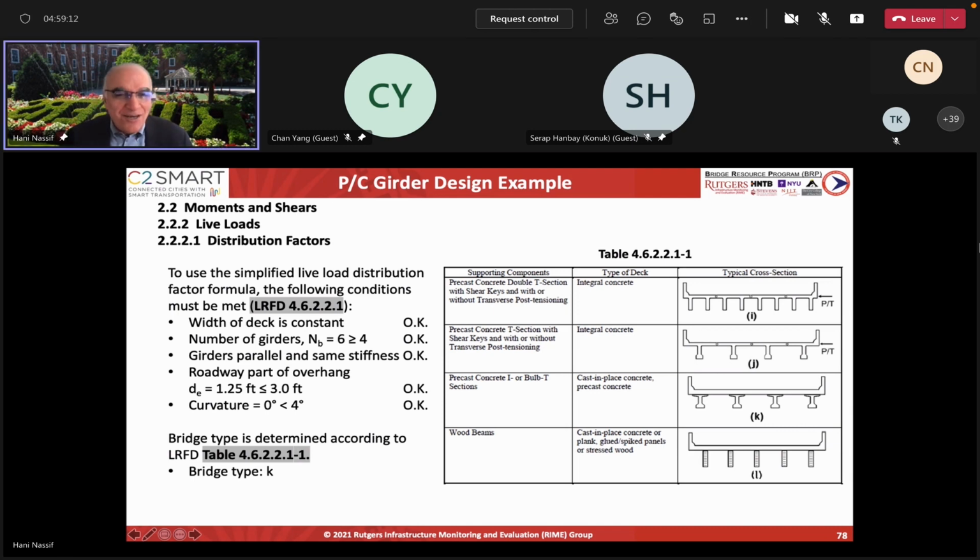Anyway, I think, Ali, you are revealing one of my exam questions. So usually I give that as an exam. Usually that case might be when you have a 3-lane bridge coming into a 2-lane bridge and then a flyover. So maybe you're starting with 12 feet girder spacing, and then at the end of the girder, you might end up with 9 feet, and then you might go even to about 6 feet.